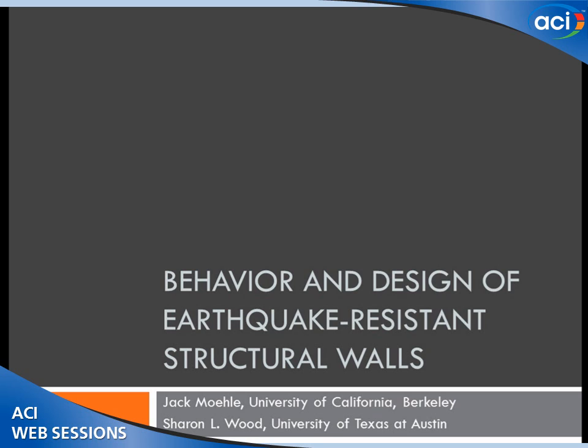Because we know that once you reach the flexural capacity in those walls, the cracks are going to reorient themselves, and as long as the walls are not overly reinforced and cause the diagonals to crash, then you can reorient, be able to reach from one mode of failure to the other. Is that reasonable?